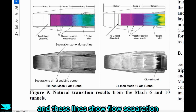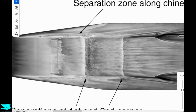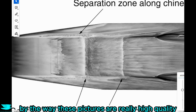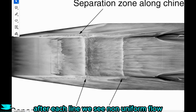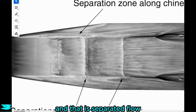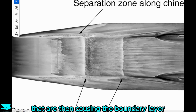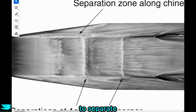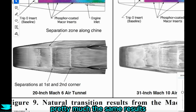And these lines show flow separation because if we zoom in, for example, just here, and by the way, these pictures are really high quality, like awesome quality. Anyway, after each line, we see non-uniform flow, and that is separated flow. So it's indicating that potentially there are shocks forming that are then causing the boundary layer, this laminar boundary layer, to separate. So it is good that both of these wind tunnels are showing pretty much the same results.